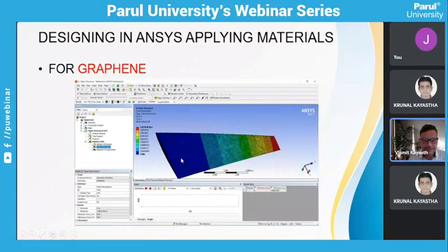So regarding the analysis part, we all know that the highest load that has been taken ahead is through the end part of the wing. Okay, that would be taking the highest part, and the red here symbolizes the total deformation. I hope it is quite visible. It's the static structure deformation.